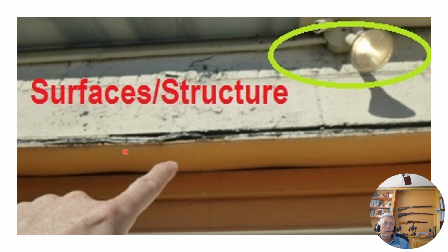This is above the lintel. See how that lintel is wavy? You see that a lot in these big commercial buildings. We have these big lintels. I've read a lot on this subject, and most people agree that it's thermal expansion, where the sun hits it and the metal expands and it warps like that. And then you got this gap up above here. So that's a defect for the report that needs to be filled in with mortar or whatever.